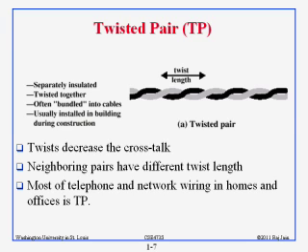Right? So if you are trying to send on two wire pairs, this will transmit and this will receive, and this will receive and this will transmit, and there will be a lot of interference. The way you minimize that is by twisting them together. So we take two of them, positive and negative, and we twist them. The more you twist, the less interference into other cables there will be, not only from them to others, but also from others to them.